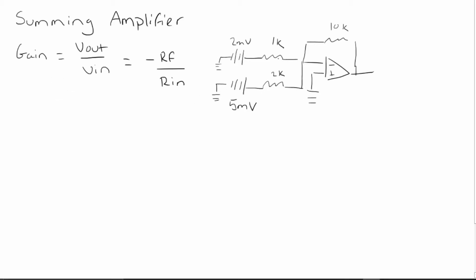So we have the formula here for the inverting amplifier, because if you take a look at this, we have our non-inverting pin connected to ground, we have the negative connecting to these 2 voltage sources through resistors, and this does resemble an inverting amplifier. So we can find this out by substituting each one into this equation, and we'll be able to find out what our total voltage is.